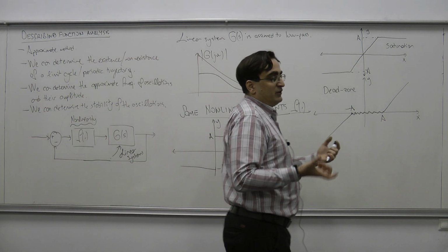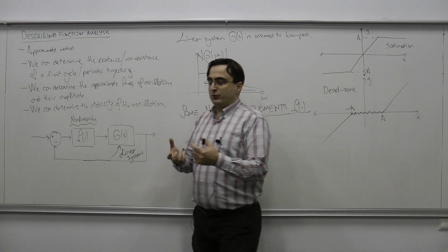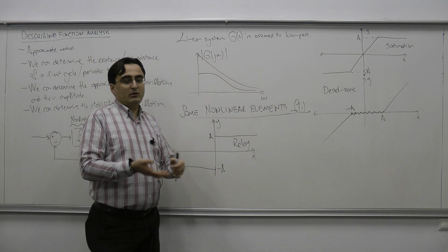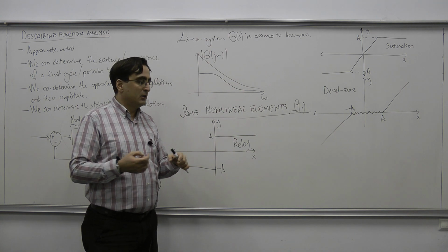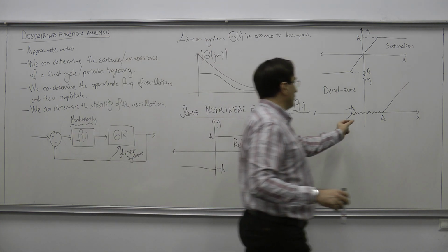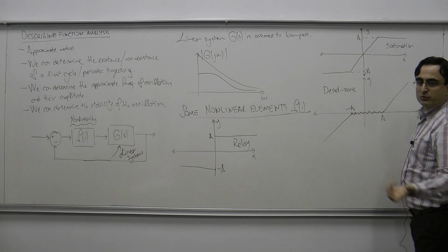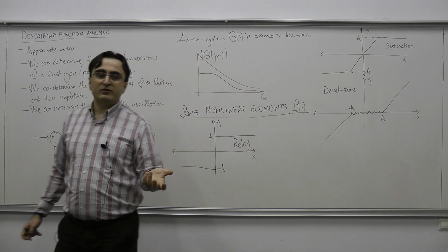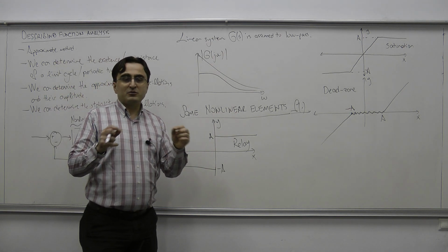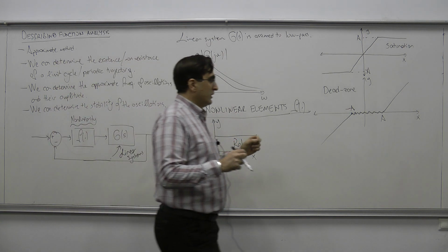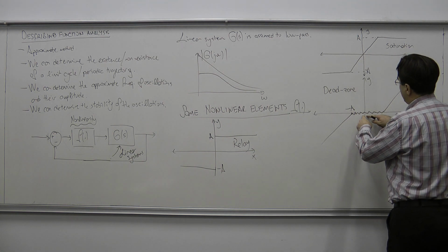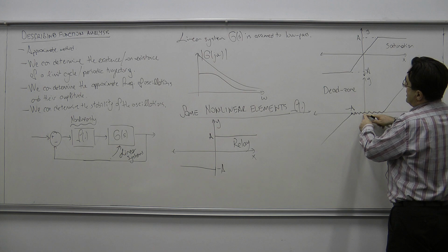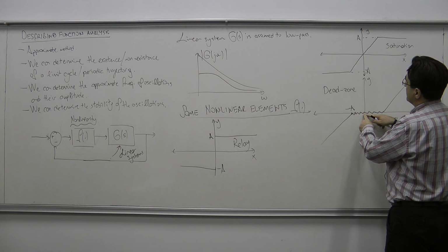So if you take a DC motor, for example, if you apply a small voltage to its terminal, voltage epsilon, for example, you will see that for small voltage values, the DC motor will not actually turn at all. So it's going to give you 0 velocity initially for some small voltage values. All right? If I increase the voltage from 0 to epsilon, the motor will not start moving immediately.